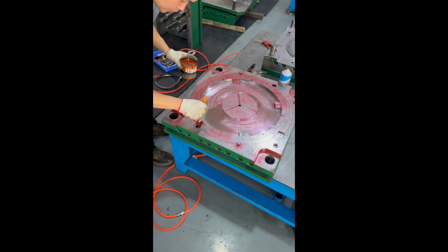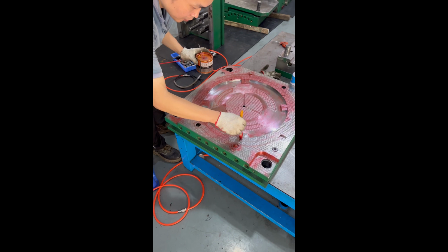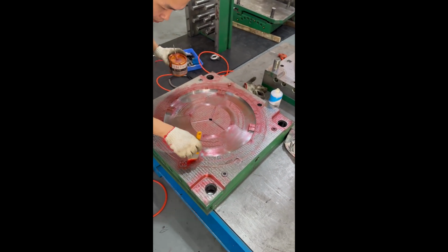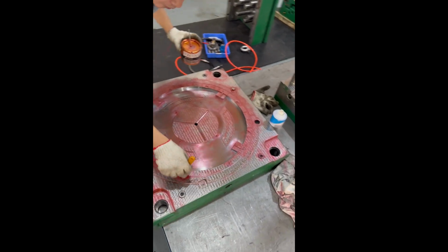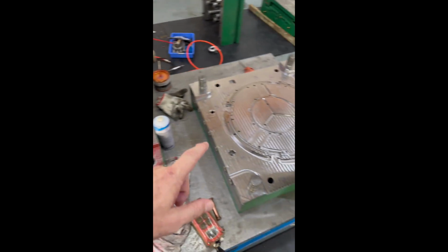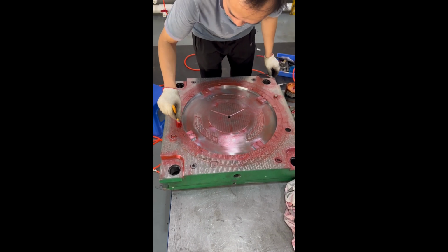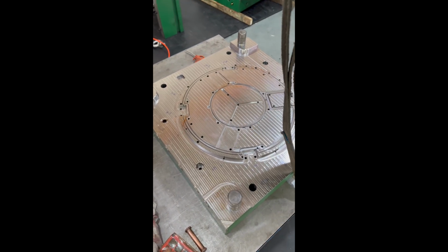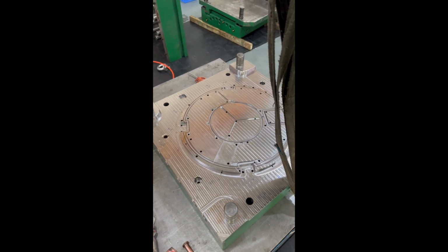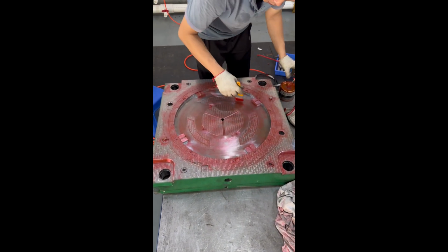So what's going on here is the guy's putting on some marker or engineering red or engineering ink, whatever it is. Basically, as this part is assembled to this part, it'll be put down, and any touching points will be showing up red on here. In other words, any high points in the steel will show up on here, and then it needs to be hand finished or polished again, such that we get an even surface. So ultimately, what we're looking for is this whole surface to be completely red with no marks, with no gaps in the marking. So that's the idea of what all this red ink is about.